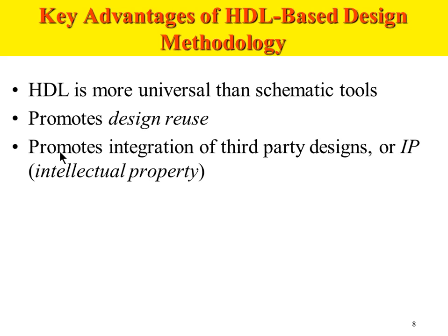HDL is more universal than schematic tools. Obviously, HDL is a language, right? So the language is much more universal. It's a free language. Nobody owns the language. It's an IEEE standard, basically. So the language can be used by anybody. It promotes design reuse in an IP format. If you remember, we talked about IP cores when we saw the initial design methodology.